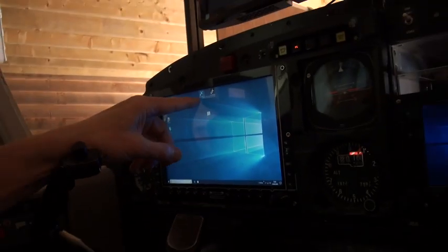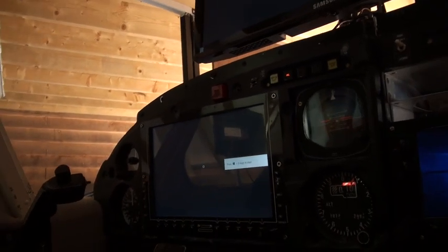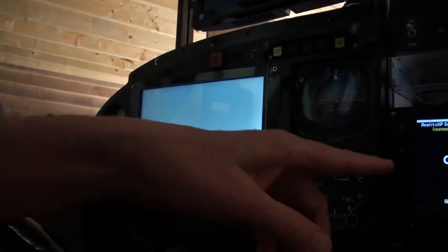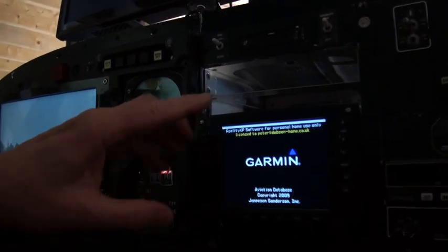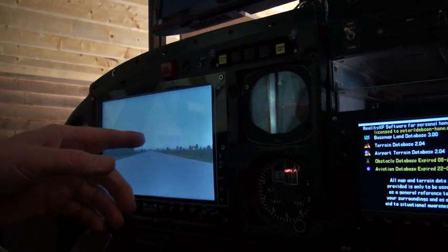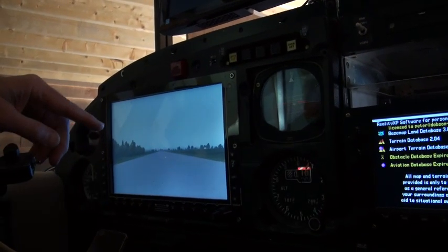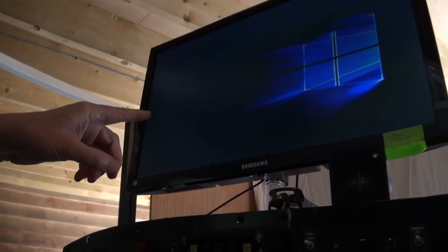So you now double click on the X-plane icon, and then everything disappears, and it'll now take about a minute or so for X-plane 11 to boot up. So you can see the GNS 530 is fired up, and you're getting a startup message here. So that's correct, we don't need to worry about that anymore. But you see what's happened, although I configured it previously to show on 2 screens, the main projector screen is still showing a Windows screen, it's not showing X-plane.